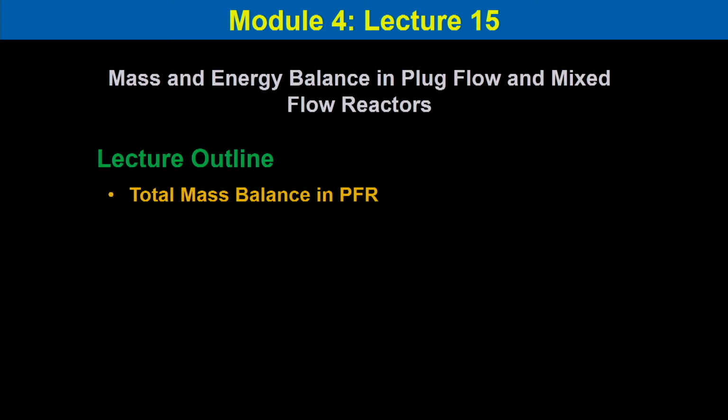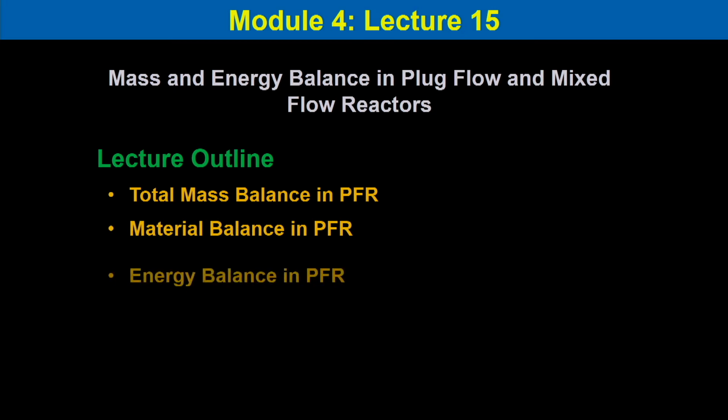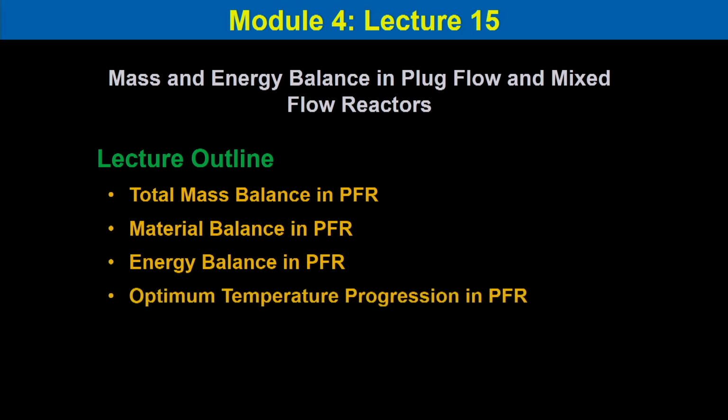We will consider total mass balance in plug flow reactor, then material balance in plug flow reactor, and particularly energy balance is our interest when we look for temperature and pressure effects. So, energy balance in PFR, then optimum temperature progression in PFR, then we will consider similar mass and energy balance in mixed flow reactor or CSTR.